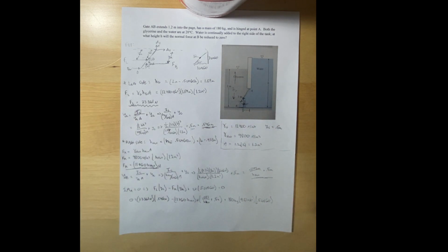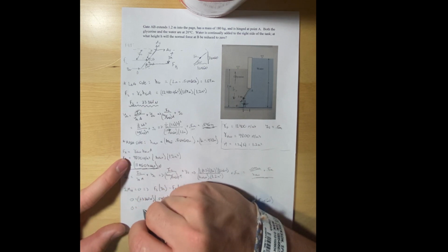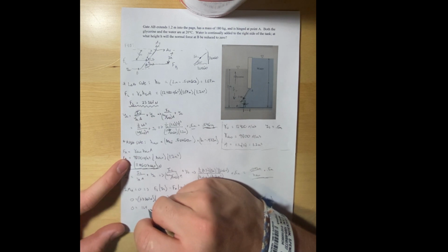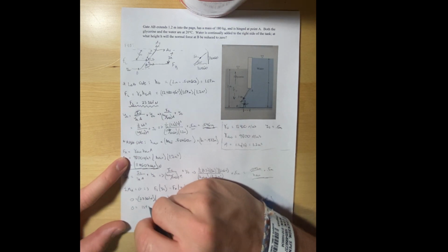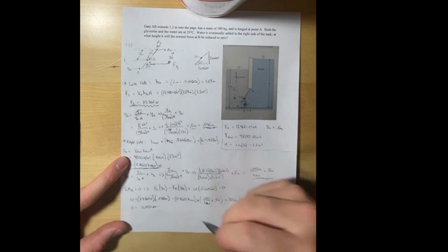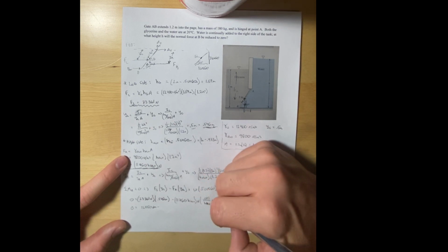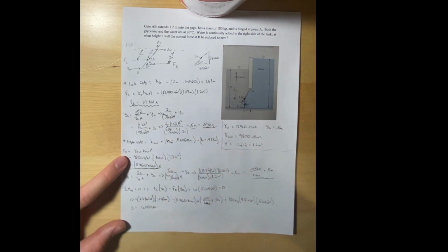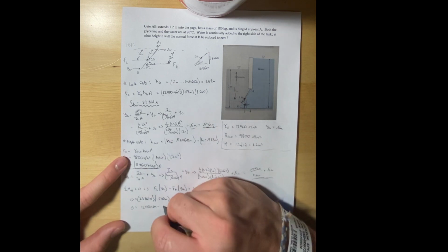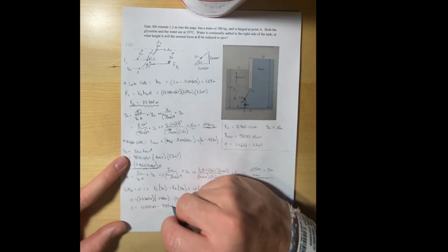All right, so doing that, that's going to give us, plugging in, 12,750 Newton meters minus, these two H2O terms are going to cancel, but you're going to be left with one remainder, given this 0.5. So we're going to get minus 847 Newton meters.